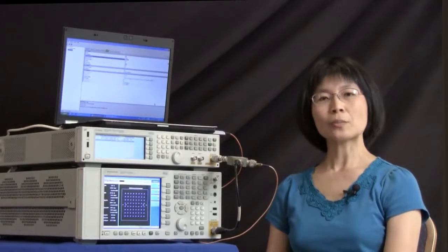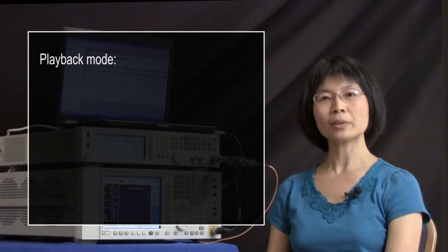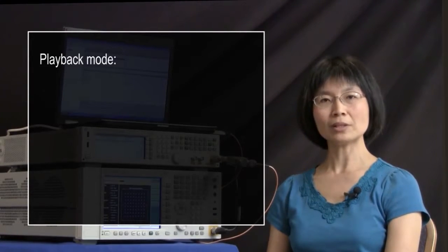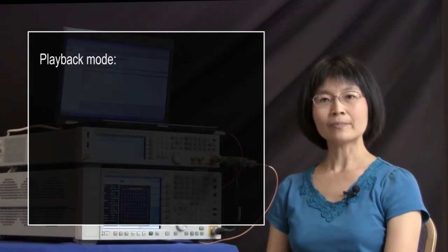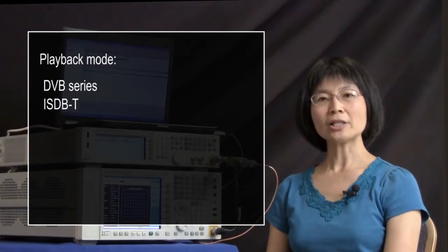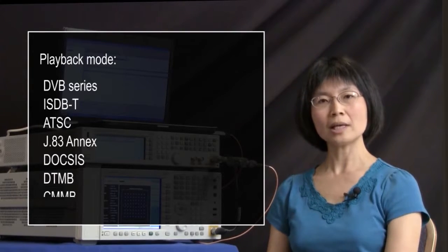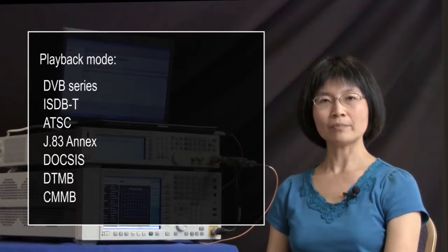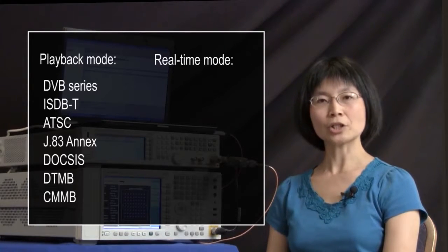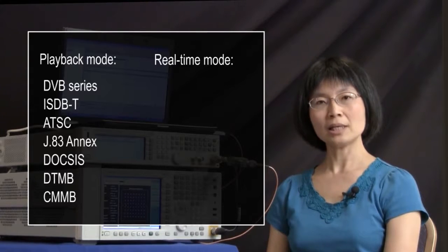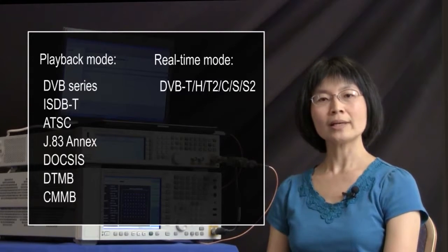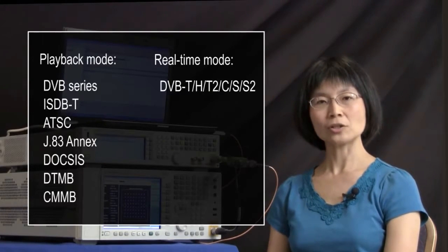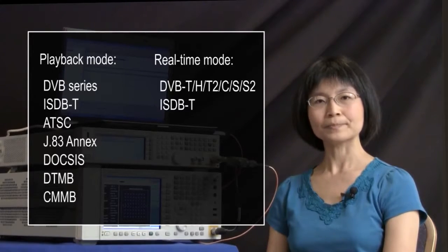This solution supports most of the standards with waveform playback mode, including the DVB series, ISDBT, ATSC, J.83 Annex, DOCSIS, and the Chinese standards DTMB and CMMB. It also supports several standards with real-time signal generation, including DVB-T, H, T2, C, S, and S2, and ISDBT.